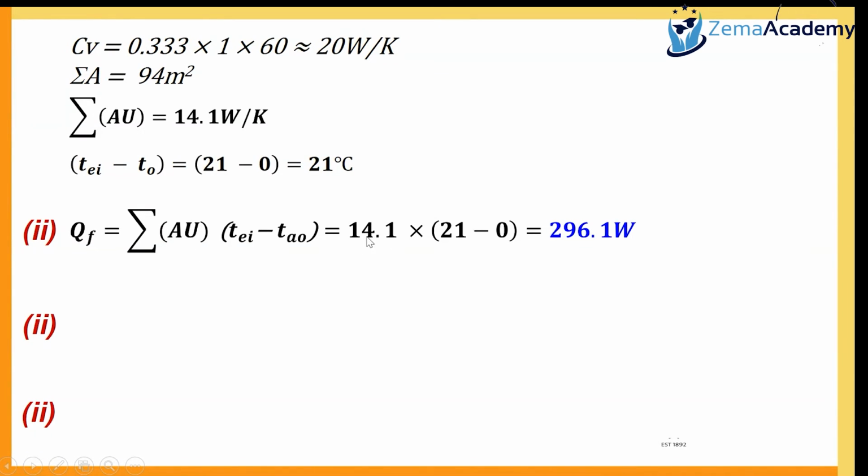This part is 14.1 and this temperature difference is 21 minus 0. So the fabric heat loss is 296.1 watts.